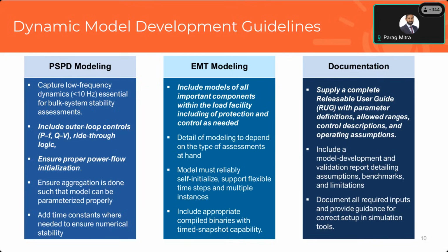And these are certain things that one has to bear in mind for EMT modeling: include all important components within the load facility, including protection and control as needed. Like I said, EMT is more of a blank canvas, so you need to know the kind of studies you're trying to do and make sure that you've modeled all of those things. The level of modeling detail depends on what type of studies you're trying to do.